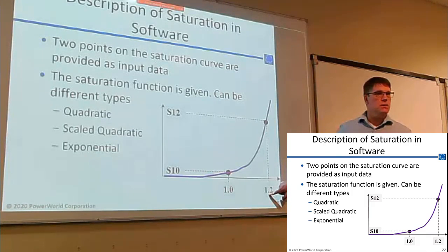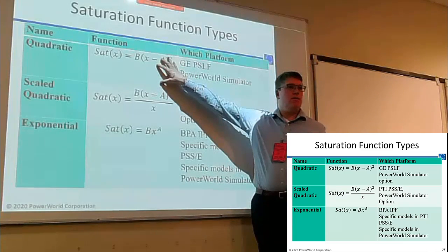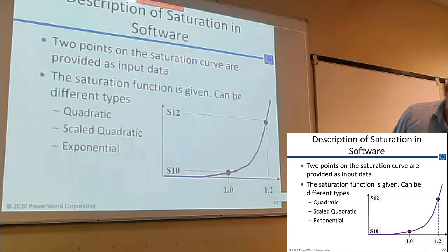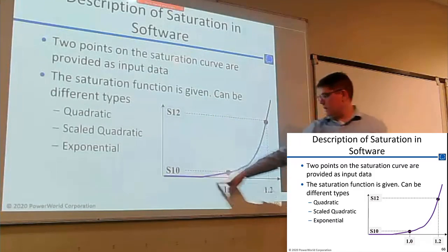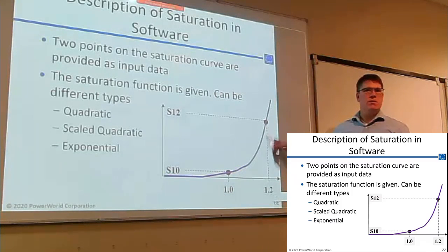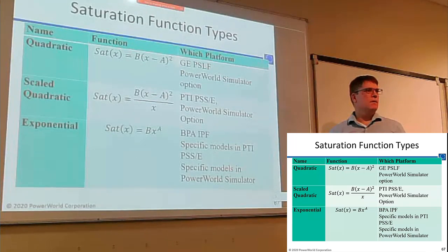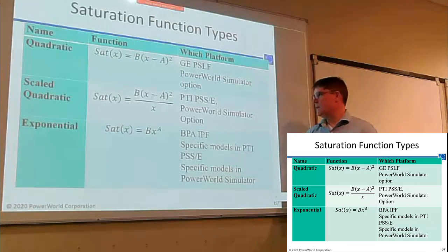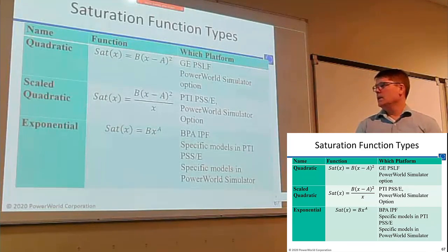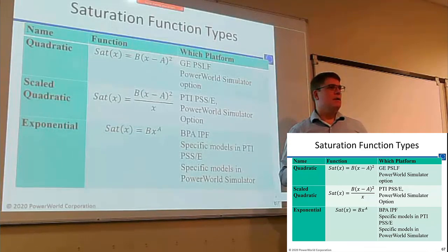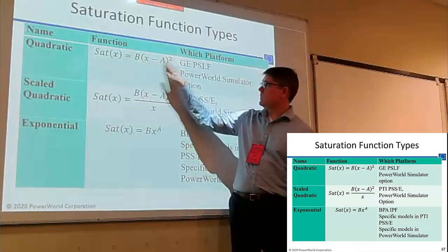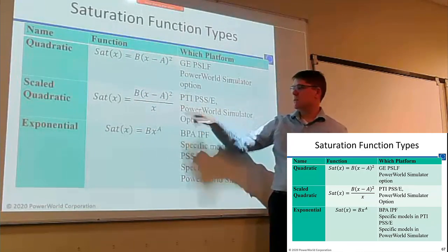And then you have to pick a function that describes how the extra current needed varies as you increase voltage, and you just define the shape by a function. One of the things that Tom found out when he did that BPA funded project, I think back in the early 2010s, when Tom was validating PowerWorld, PSSE, BPA's old tool, PSLF, was that the software tools don't use the same function. Right, Tom? We found out that PSLF uses this function and PTI uses this function. As long as you're in between, it doesn't matter that much, but you will get different answers.